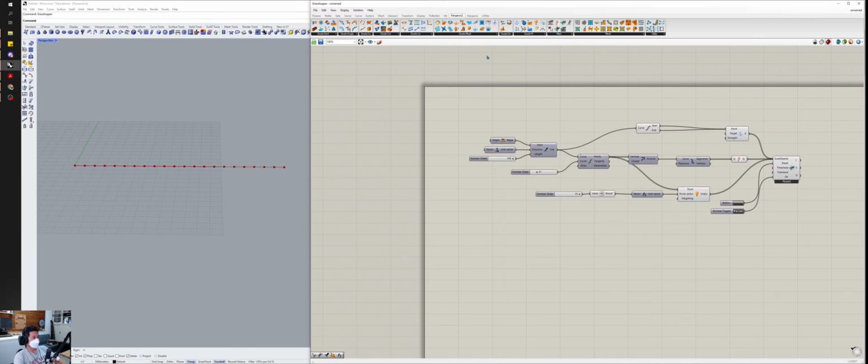So we got to go to our Kangaroo, and we know that's a line geometry. So we're going to go to our goals and line, and we're going to pick one of these characteristics. In this case, let's use the line length, which is also a spring force. So this will allow us to define that segment of string in terms of how stretchy it is, basically.